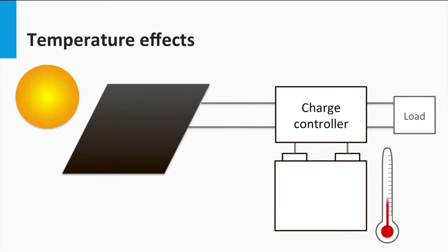A good charge controller these days comes with an inbuilt temperature sensor. Therefore, it compensates for temperature fluctuations and dynamically decides how the electrical specifications like operating voltage change with temperature. It successfully keeps the battery operating in the desired range of voltages depending on the temperature.